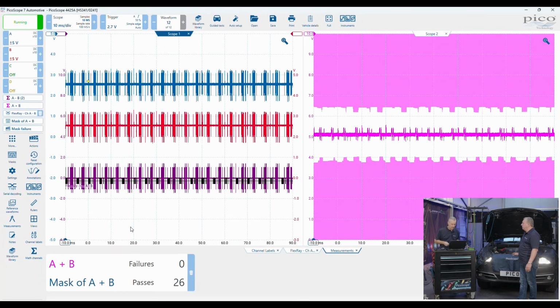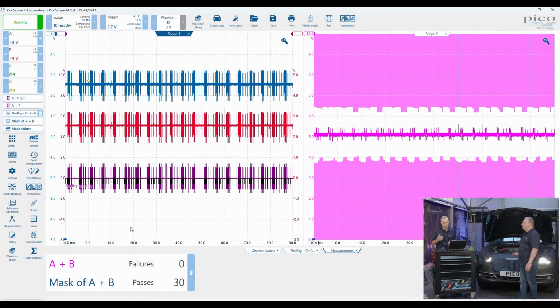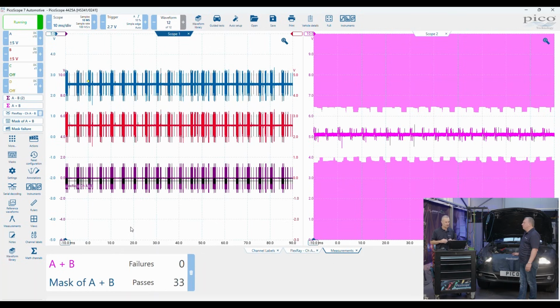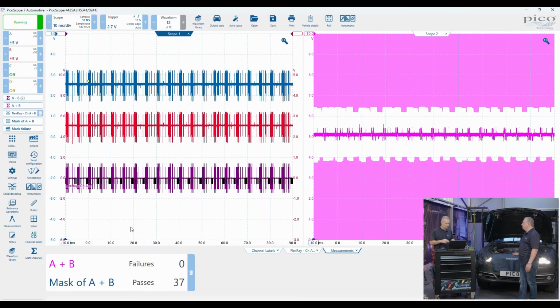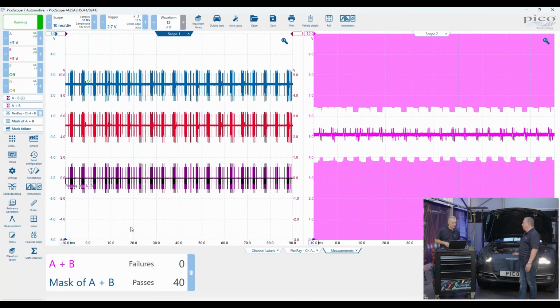Obviously, you don't road test on your own, and you can't be operating the laptop and driving at the same time. But you could have this configured before you set out on road test, so that you can do what you've got to do, generate the fault. When it's safe to do so, pull over, review the data. But wiggle testing, yes, absolutely perfect.